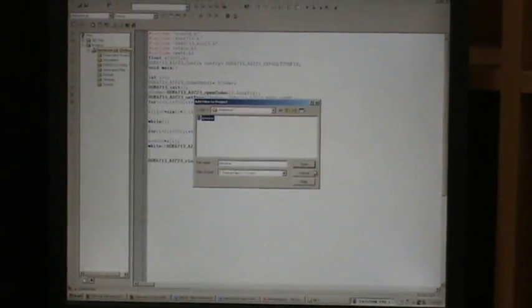So this is the sine wave code. Save it with Ctrl S and add it in the same folder, same project name, sine wave project. Add files to project, sine wave, open. So it's already added here. We have to make sure we include some board support library files. One is the DSK 6713 header file, another one is the AIC codec file, and one board support library file.